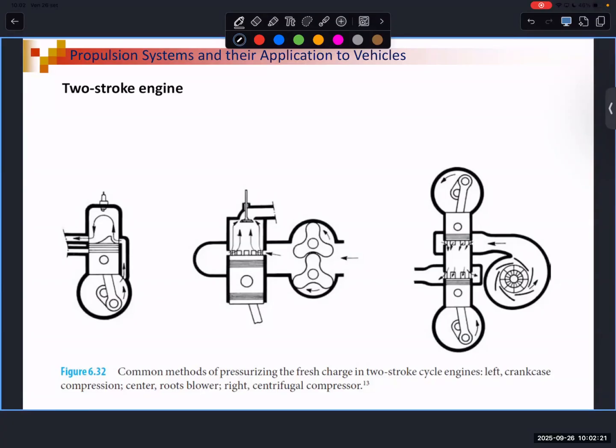Sure. Is the first the petrol engine and in the center the diesel engine, right? I mean, here the engines can be either gasoline or diesel. So here they are two strokes, and two strokes can be either spark ignition or compression ignition. So this doesn't mean that this is a diesel engine. Could be a diesel engine, but this can be a general configuration. So for two strokes, we can consider either compression ignition or spark ignition because the two criteria are completely independent.